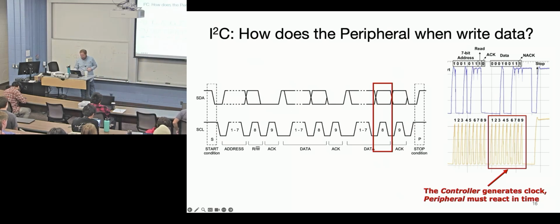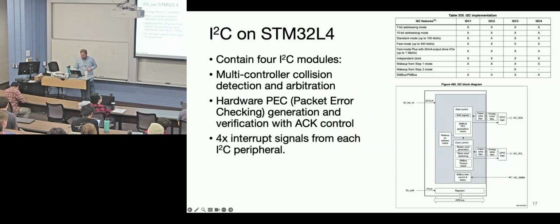I know we covered most of these concepts already. Okay, so your STM32 has 4 I2C modules. Now, you will read through the data sheet and see that some of these pins overlap with your SPI module. It's not like you could actually have 3 SPIs and 4 UART, 4 I2C, but there's up to 4 I2C. So maybe I'll ask you this. Take a minute or so, think about why you'd want to have multiple I2C peripherals or modules on your device.